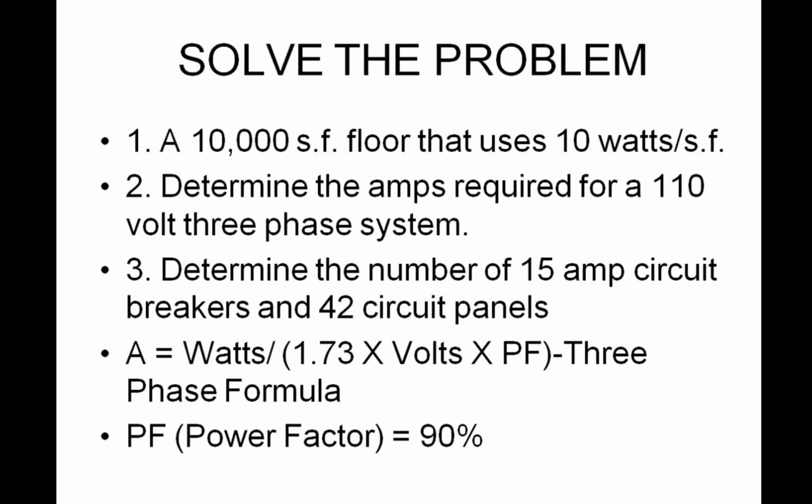So here's something that could appear on an exam. A very simple calculation that gives you an idea of how these circuit panel breakers are planned for in a building, knowing what your loads are. Given in number 1, you have a 10,000 square foot floor. So it's a large office floor, let's say, and the average usage on that floor is 10 watts per square foot. Let's just say that's a standard engineering calculation for what's expected on this floor.